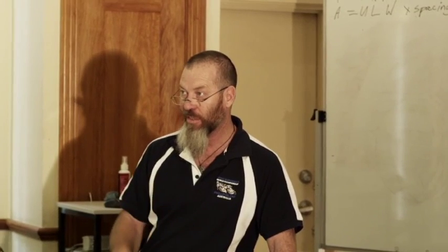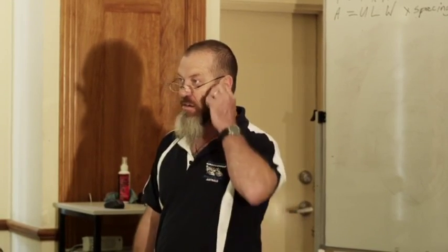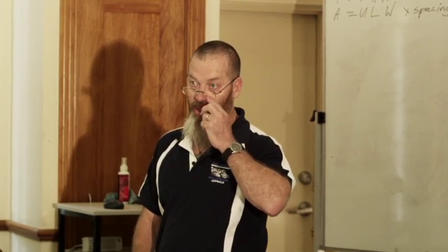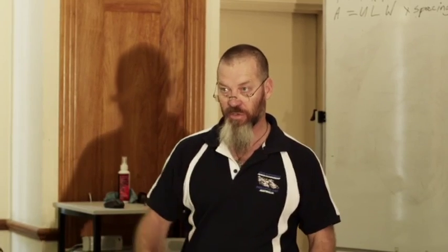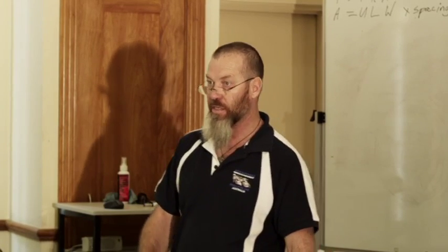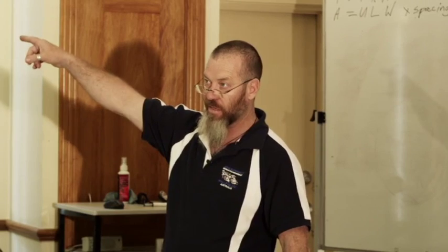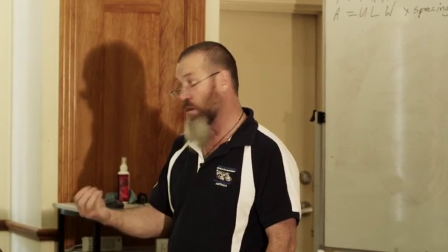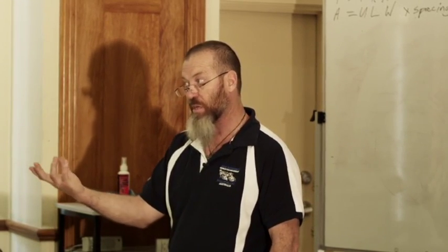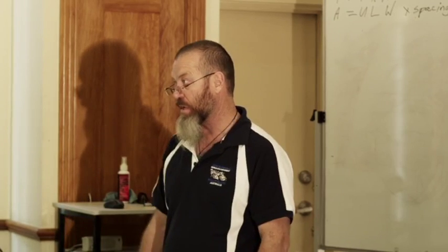I need you to ask him what nails are going to be used for edge battens and what nails are going to be used for general area battens, and you watch him. So you need to bring this to his attention. You've got to say to him, look, I'm sorry, mate, but when I actually calculate this, you've given me a price to fix this roof. When I've calculated this, and you should know this, deformed shank nails on the edges, plain shanks in the general area. That's real life. I'm only talking N2, I'm not talking about N3 or up in the seas where our mate is in Cairns. So that's the truth.